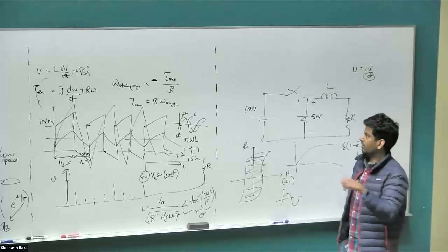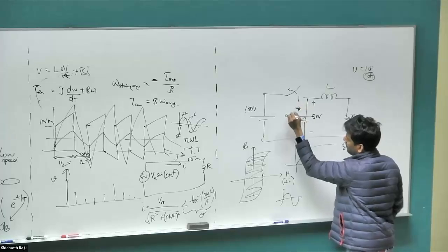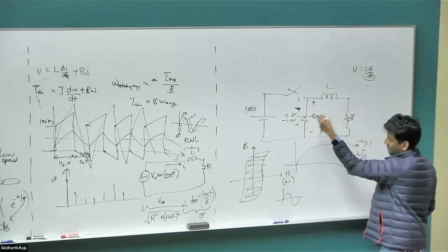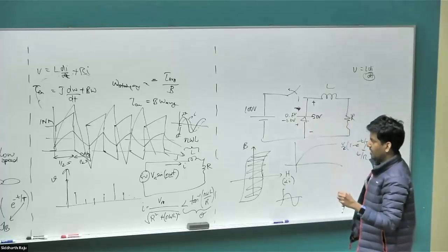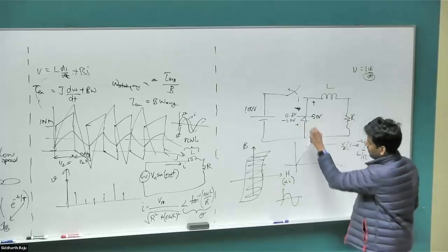Quite lossy. A power diode could drop about 0.7 to 1.2 volts when it's conducting. And if you have 50 amperes of current, that's 50 watts of power drop right there. It's a thermal management issue and of course an efficiency issue. So what is the solution?